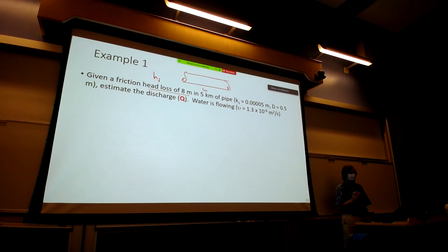That would cost a few $100,000. What would be much cheaper? Measuring the pressure at two different locations, just like you did in fluids lab, and then you can estimate the discharge. It's a lot cheaper. So this is actually a real problem, and distribution networks and other pressure piping systems will use pressure drop, just like you did in lab, to estimate discharge.